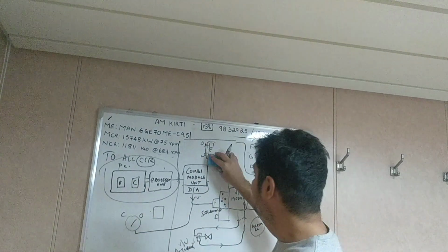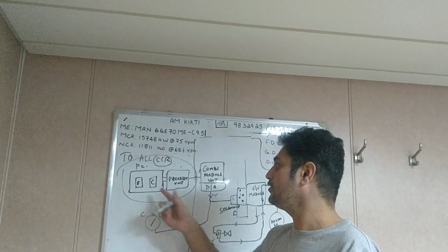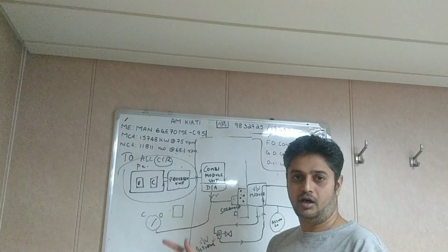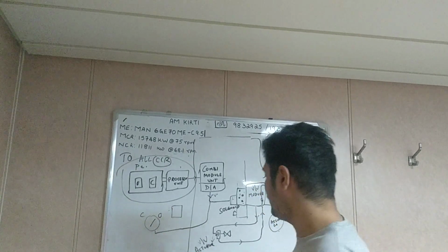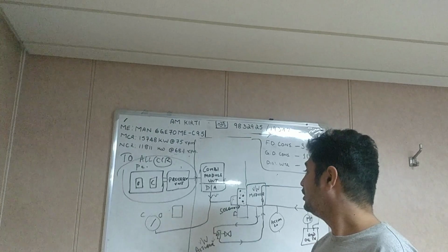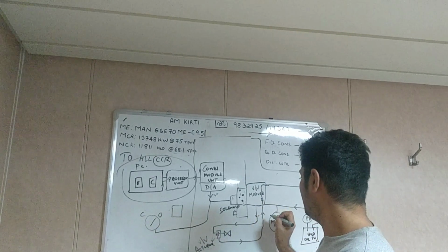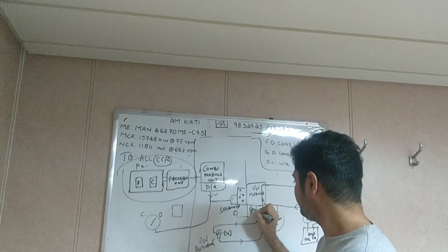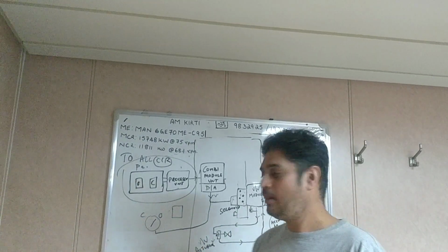Another way of getting the feedback, feedback in the sense open or close, or whatever signal you gave, how the system has responded, you need to know. So another way of achieving the feedback is you will have a kind of flow meter wheel here. In our ship there is a flow meter wheel.